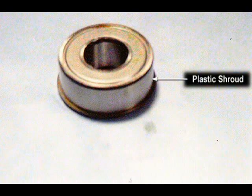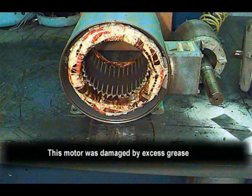Sealed, grease-packed bearings have a plastic shroud on either side to keep in the grease that was provided at the factory. These are sealed units. Lubrication should not be attempted. If a sealed unit is erroneously greased, grease could work its way into the motor windings.